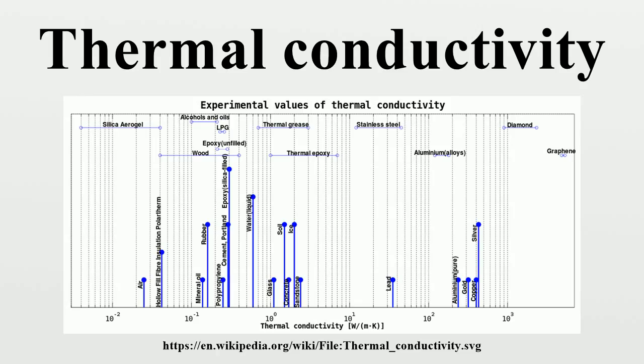Influencing factors. Temperature. The effect of temperature on thermal conductivity is different for metals and non-metals. In metals, conductivity is primarily due to free electrons. Following the Wiedemann-Franz law, thermal conductivity of metals is approximately proportional to the absolute temperature times electrical conductivity. In pure metals, the electrical conductivity decreases with increasing temperature, and thus the product of the two, the thermal conductivity, stays approximately constant. In alloys, the change in electrical conductivity is usually smaller, and thus thermal conductivity increases with temperature,